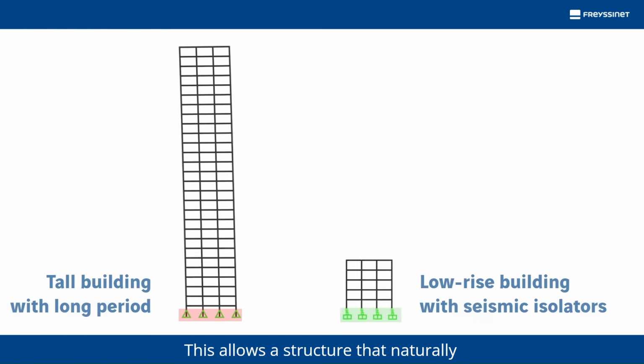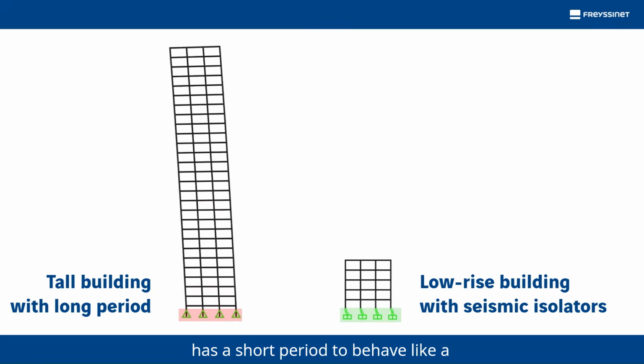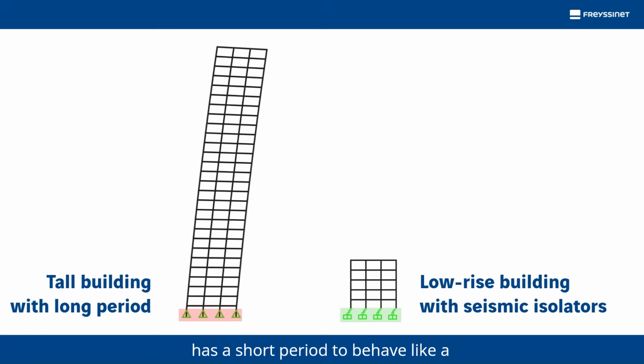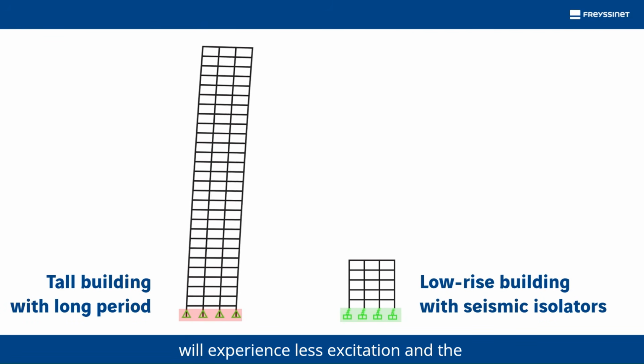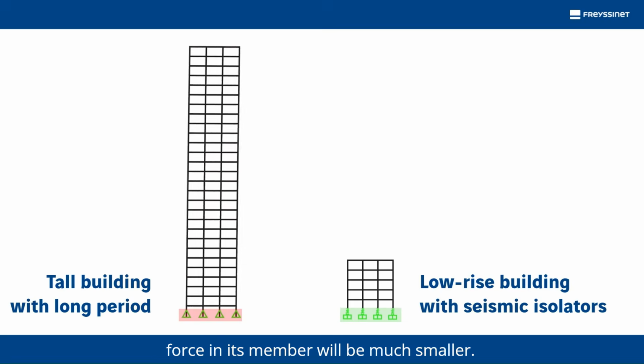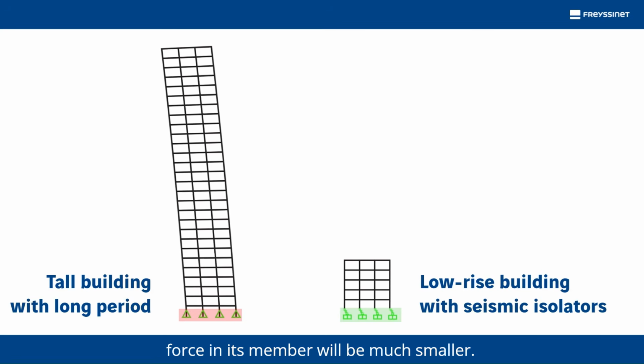This allows a structure that naturally has a short period to behave like a long period structure, where we know it will experience less excitation and the force in its members will be much smaller.